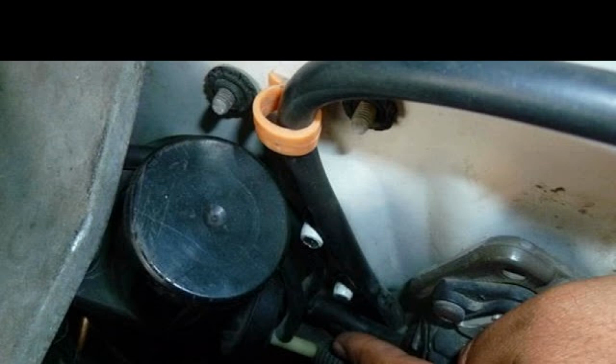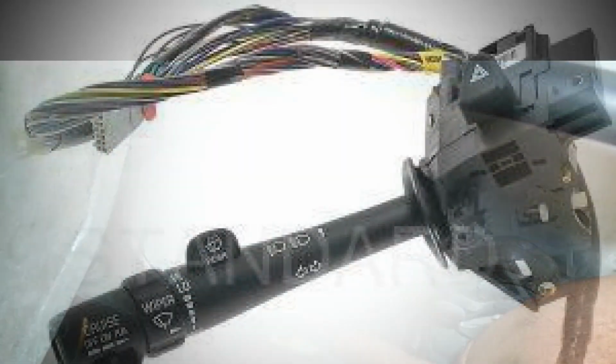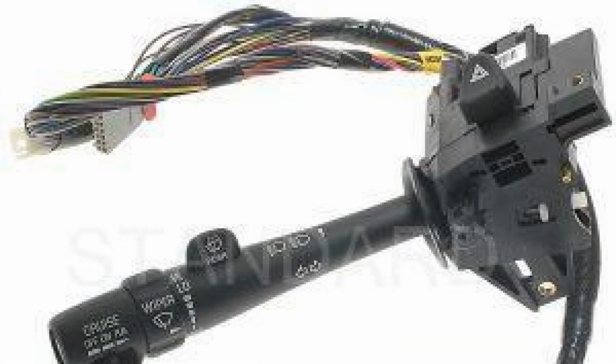Diagnosis of the P0582 code begins by connecting an OBD2 scanner to the car's computer connection. Once connected, the mechanic can read all the codes stored in the system. The mechanic will also carry out a full visual inspection of all wires and connections, as well as vacuum lines. After the inspection, the code must be cleared and the vehicle tested by trying to activate the cruise control.